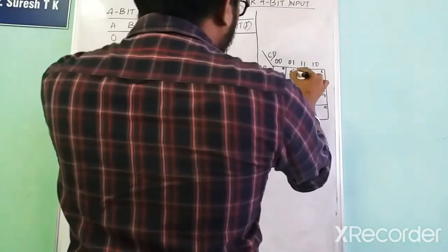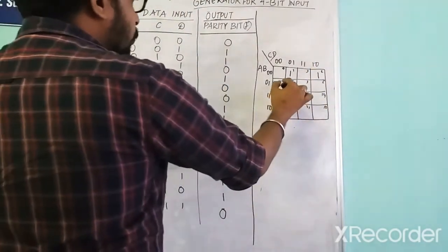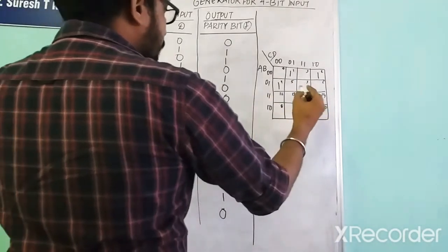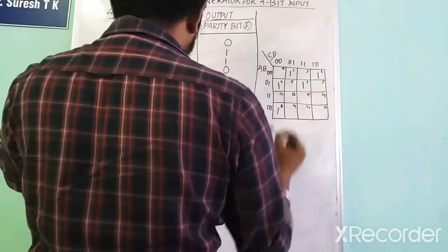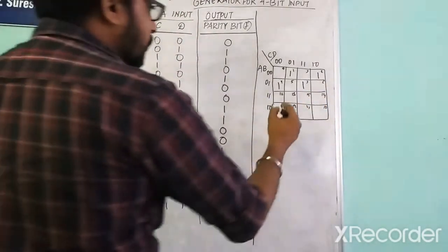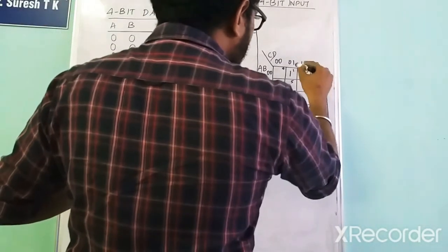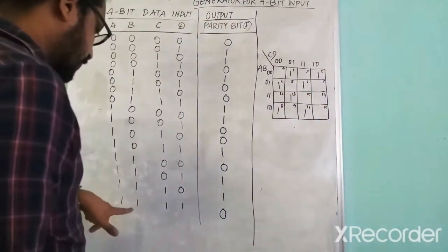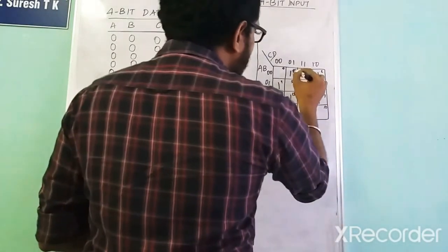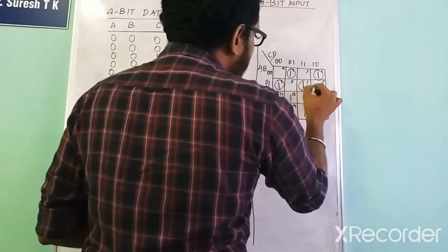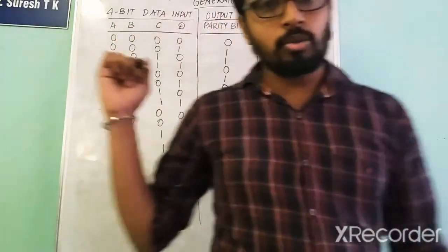For 1 we put a 1 here. For 2 we put a 1. For 4 we put a 1 here. For 7, 1 here. For 8 we have a 1. Then 1011, 1101, 1110 get ones here. So grouping means no pairs or quads, all individual cases. Okay. Please go through these steps.